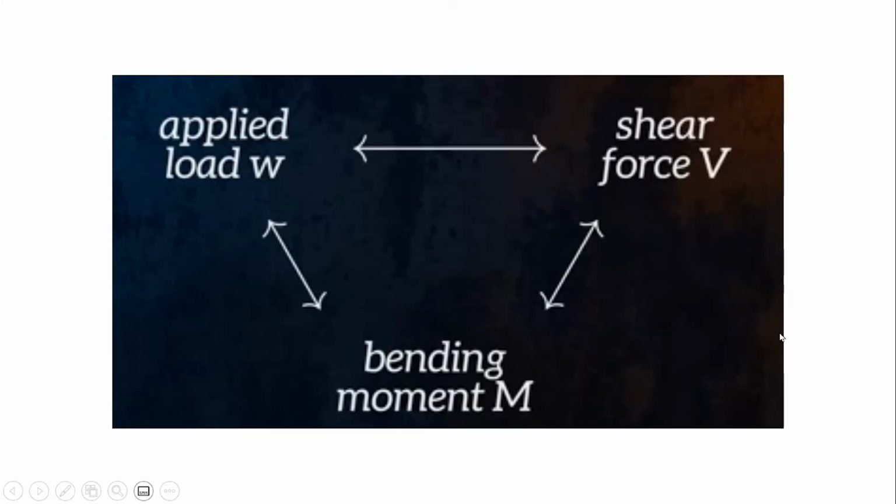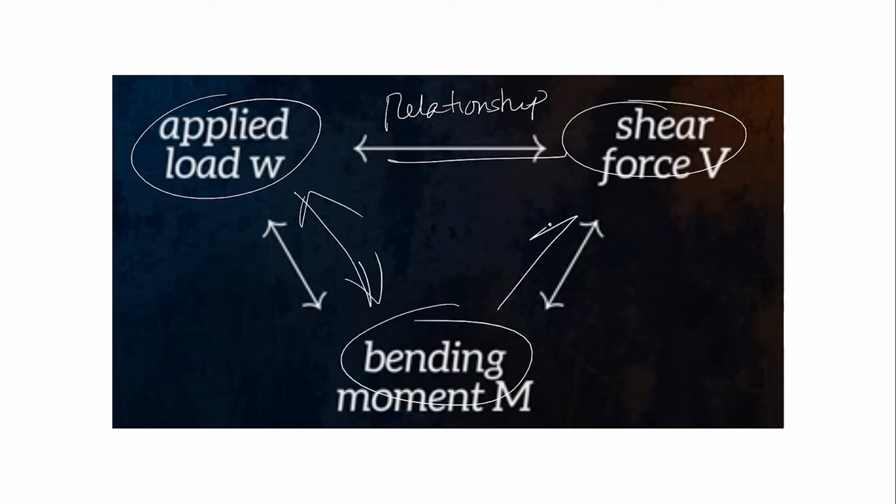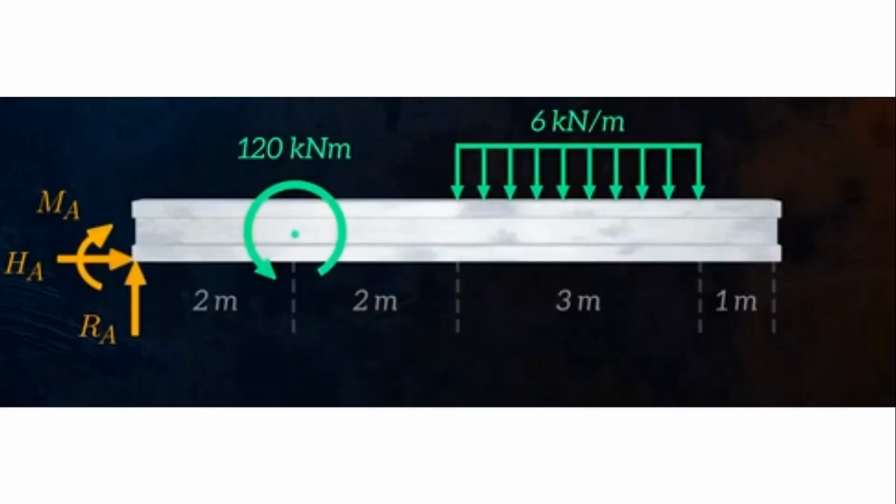So it requires practice. How do we do the shear and moment diagram? You have to analyze the relationship, the connection between the applied load, the shear force and the bending moment. The applied load relates to the shear, which is V, the vertical shear, upward or downward, and the bending moment, going clockwise which is negative, and here positive. So that is what will happen.